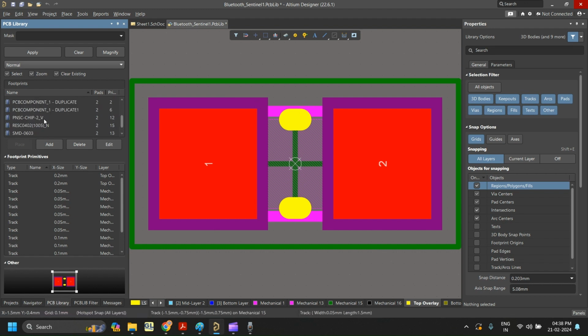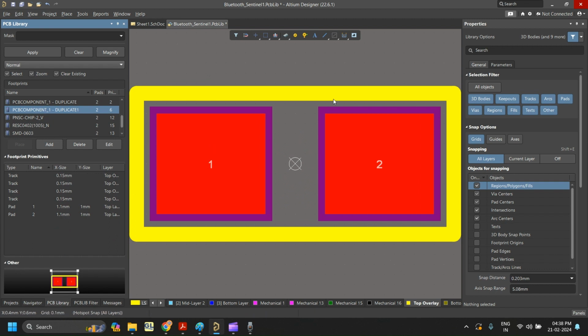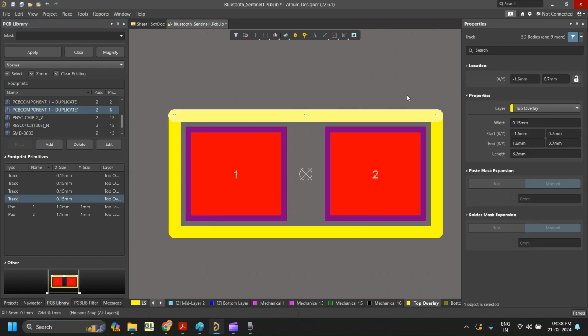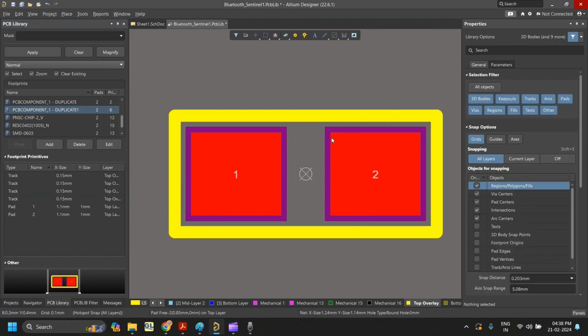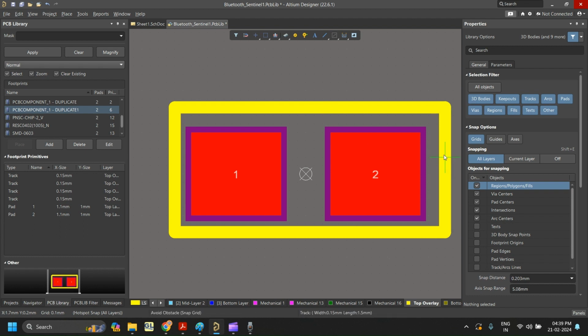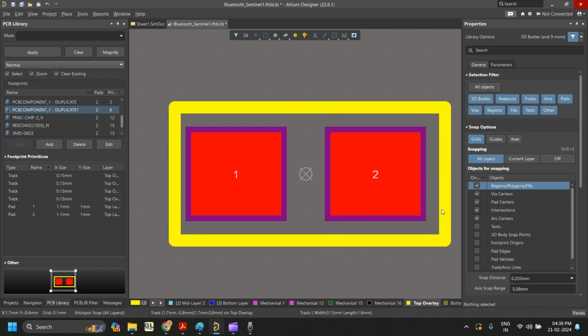Okay, so here I am going to define this. Always try to maintain a minimum of 0.2 mm clearance between silkscreen and the pad. Okay, here our grid is 0.1 mm. You can see I am maintaining 0.1 only here. So this you can adjust, and it also depends upon which type of density level you are going to use. Okay, silkscreen is defined.